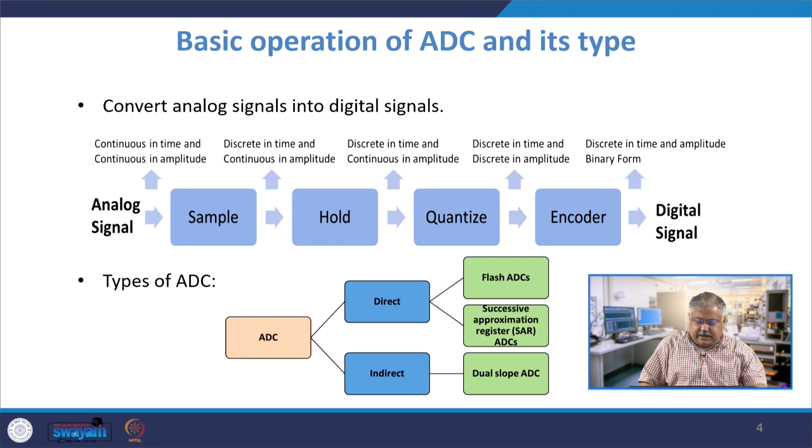Before we go to the basic ADC and its operation, we have already discussed low leakage and therefore low power of any design at low temperature, typically at 77 K, and there are fewer abnormalities when you do ADC design. We also work with these ADC designs. Please understand, we do not require a very low technology node to understand ADCs, right. Even a high technology node such as 90 nm will be sufficient to understand the various operations of an ADC. Now, if you look at the various block diagrams of an ADC,